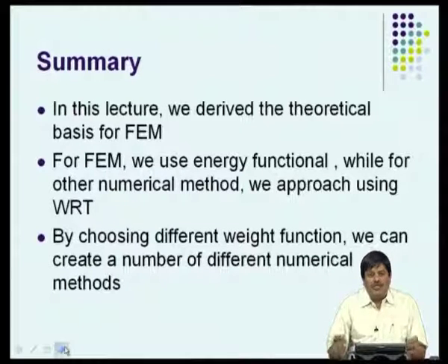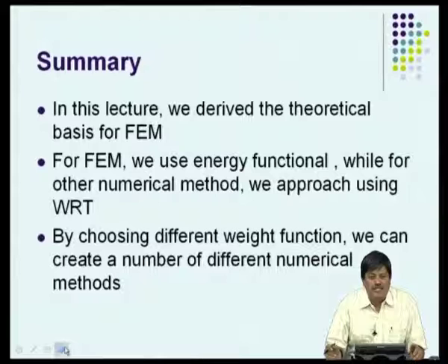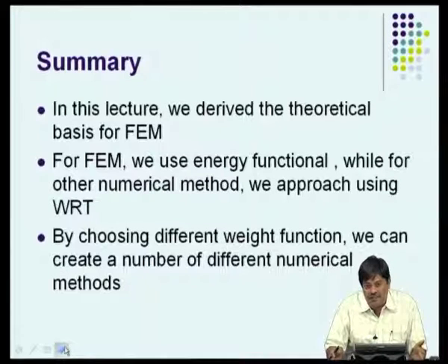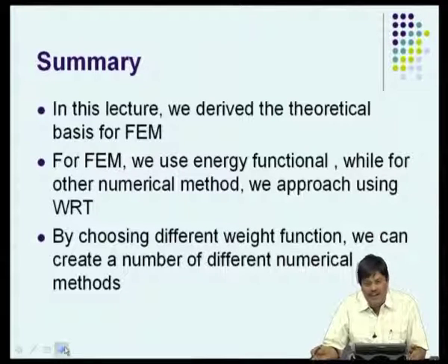So, let us summarize what we understood in this lecture. In the last lecture we said what FEM is without giving the mathematics and science behind it. In this lecture we established the theoretical basis of FEM, which is essentially a weighted residual technique. And we also established a direct relationship between the weighted residual technique and the FEM. In weighted residual technique, we take the residue and force it to 0 in some form, either using Galerkin method or least square method.